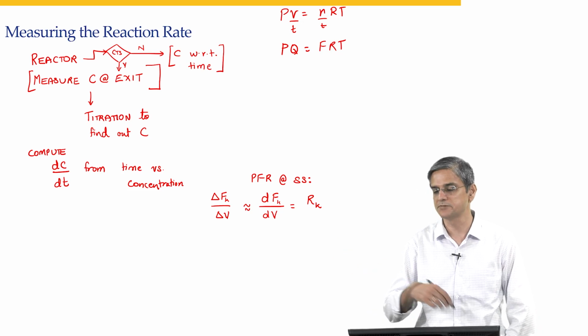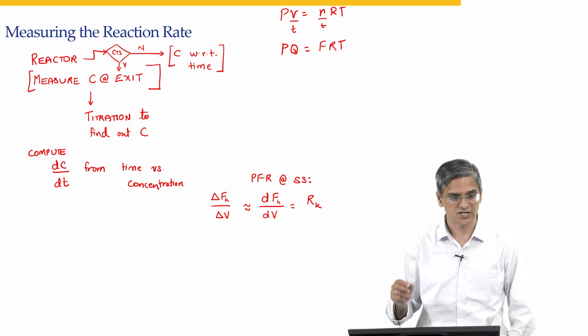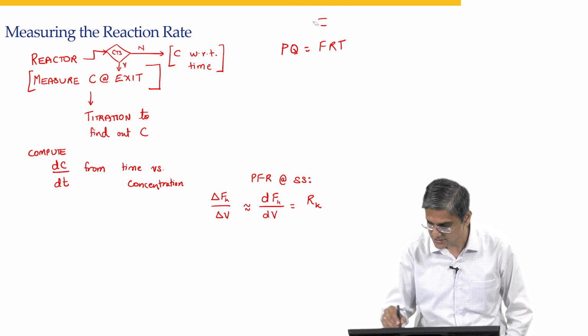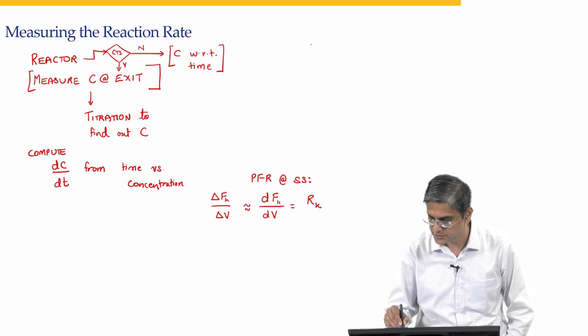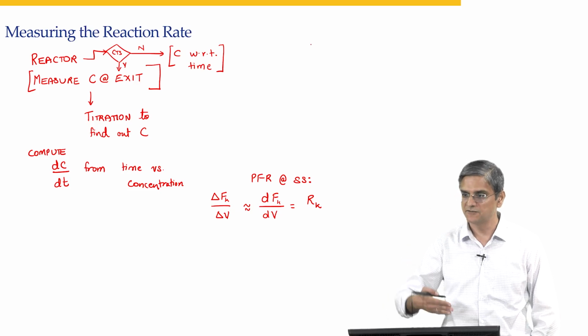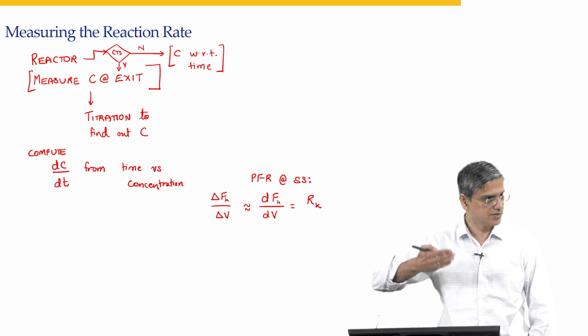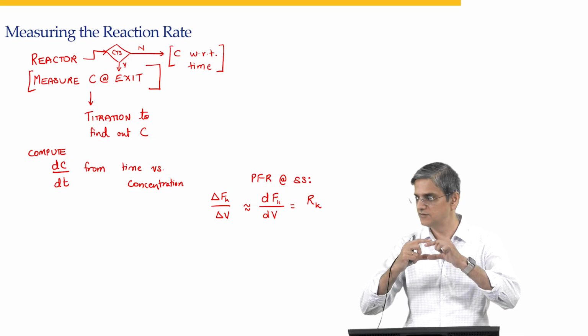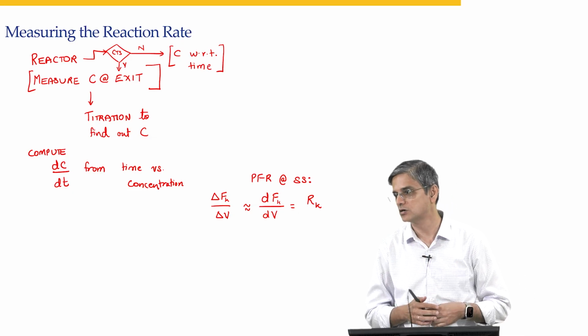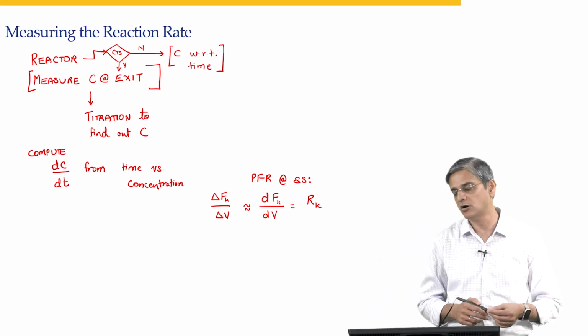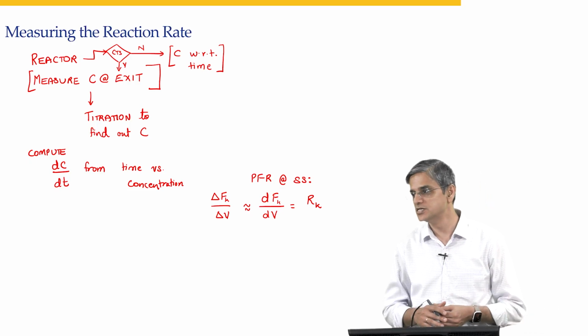So, what happens? Temperature change is reflected in volumetric flow rate change. So, the volumetric flow rate has increased almost by an order of magnitude. So, you have such a fast moving gas and comparatively such a small flame. So, your Q by V, or sorry, your V by Q is really small.